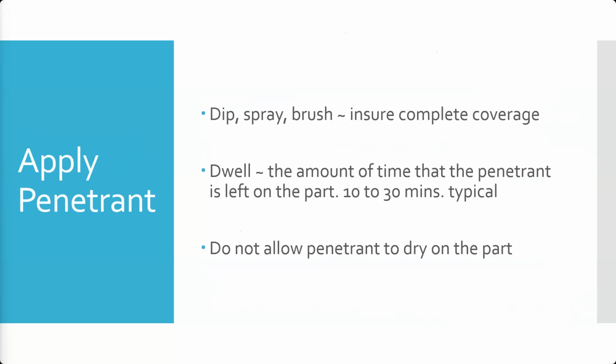To be able to determine that on a certified part, you typically have to have some material science background, and then you have to be qualified to a level 3 in that method, in LPI. Okay. To just perform LPI, like in the hangar, you're going to be a level 1. You would be qualified as a level 1. Near the end of the semester, we'll talk about different qualification levels and that kind of thing. But just know to design or figure out what procedure to use, you have to be a level 3.